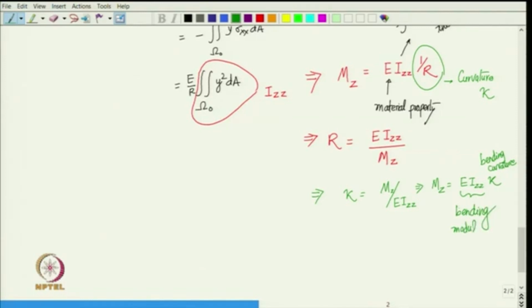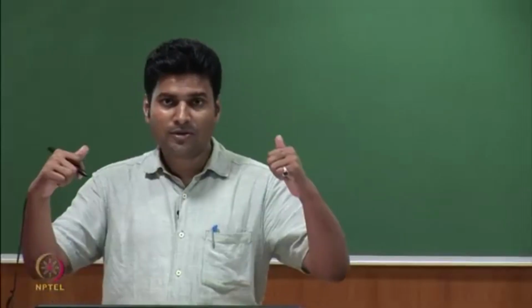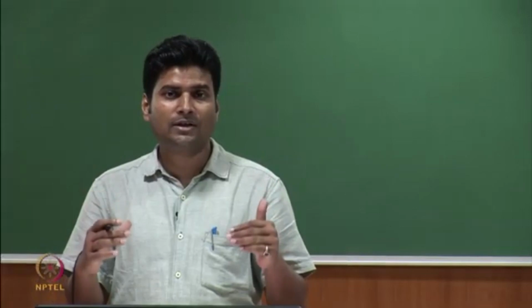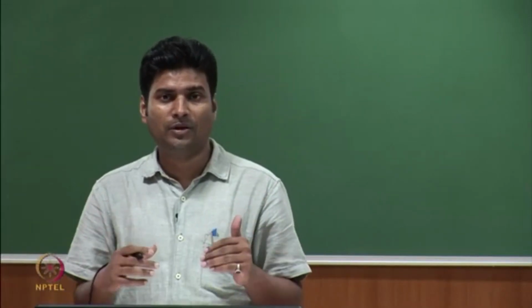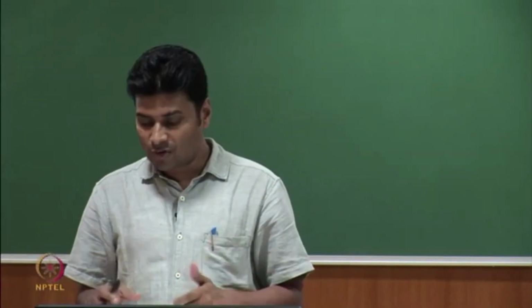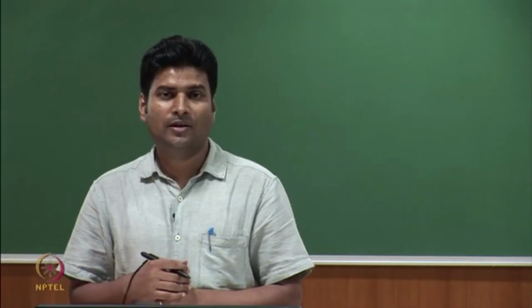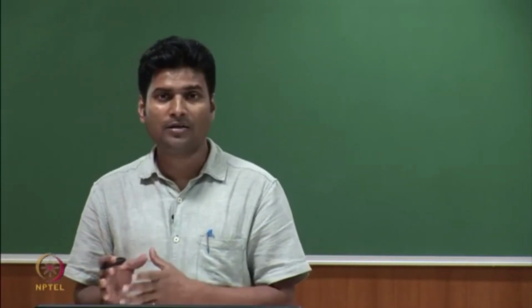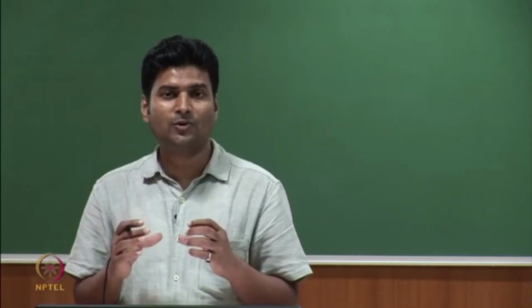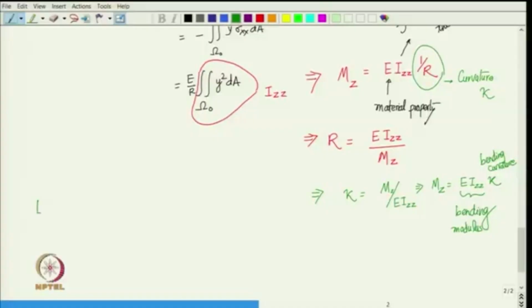So, the bending modulus of a beam is the combination of material property as well as geometric property. If we have a beam and we apply some moment, then the curvature that gets induced in the beam depends on the bending modulus. If the bending modulus is very high, then the curvature induced would be small. So, it would be difficult to curve a beam. We can make this remark here.